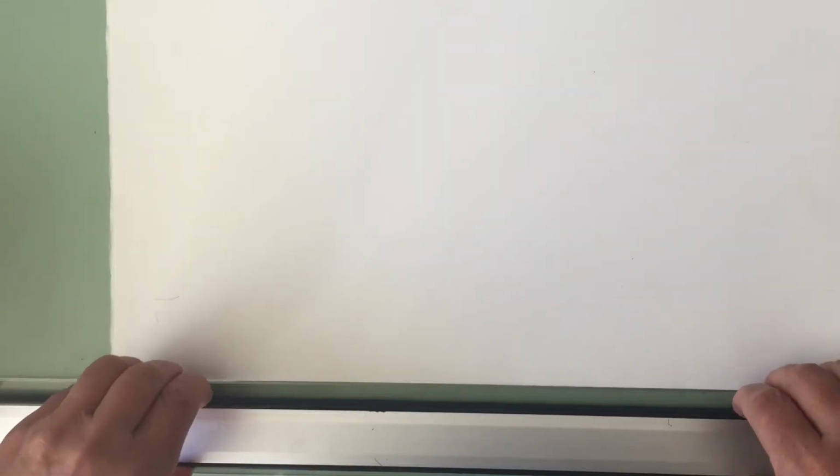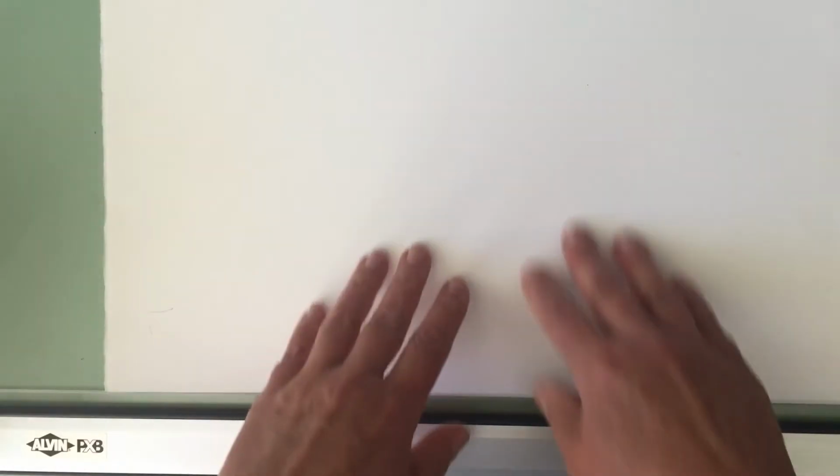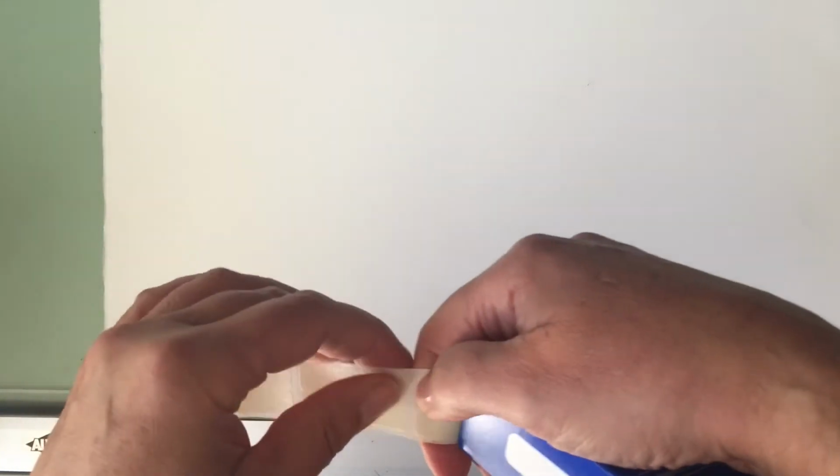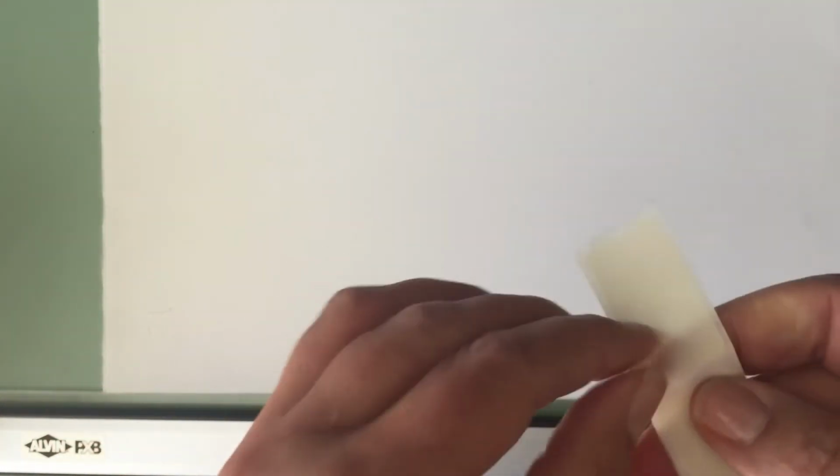All right, we're going to start to draw some lines, and they're going to be straight lines this time. And I've got here a quarter sheet of paper, and what you do to start off with is always register that paper. Always line it with your parallel rule. So we're going to take that like so, make sure it's square to that, and then we're going to tape it down. Now I use these drafting strips. Again, it just keeps everything really nice and neat and tidy. And there is an art to taping your paper down.